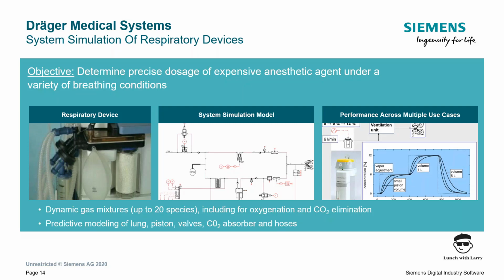Sure. And I've got a couple of questions coming in too. Maybe Bob, you could take this one. The question is, are the physics models of the pneumatic components able to model the compressibility and inertia of the gases? I don't know if you have an answer to that one. Yeah, definitely. All the volumes and components in the AIM-Sim have either a combination of resistance and compressibility as well as inertia effects. So you can look at dynamic transients.